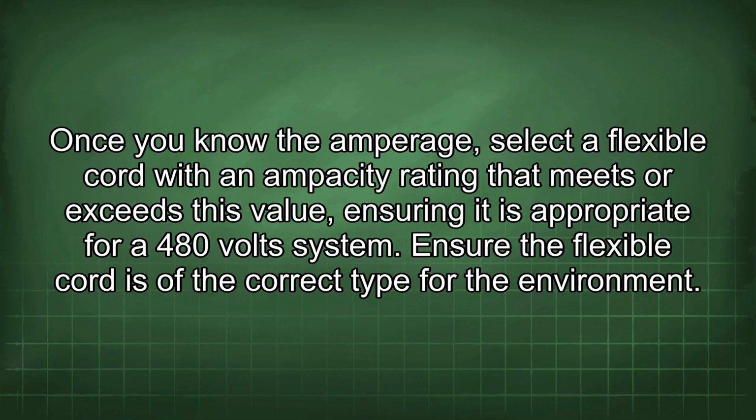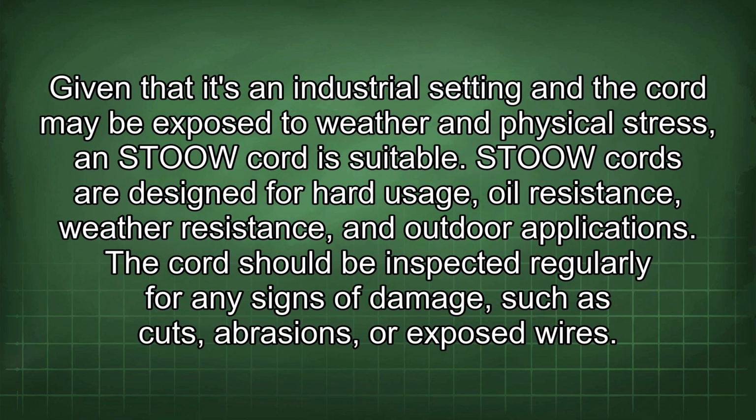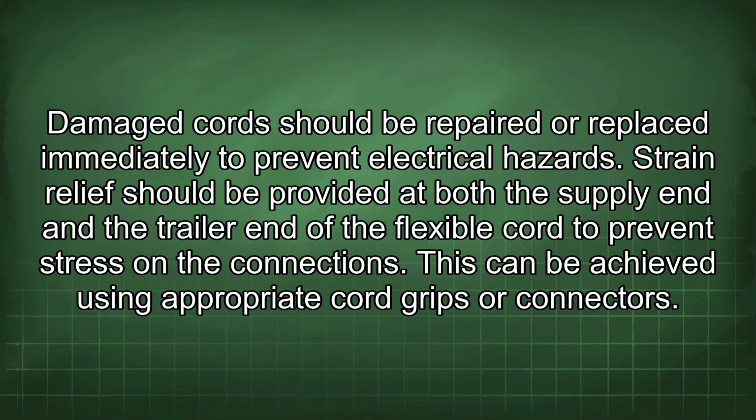Ensure the flexible cord is of the correct type for the environment. Given that it's an industrial setting and the cord may be exposed to weather and physical stress, a STU cord is suitable. STU cords are designed for hard usage, oil resistance, weather resistance, and outdoor applications. The cord should be inspected regularly for any signs of damage such as cuts, abrasions, or exposed wires. Damaged cords should be repaired or replaced immediately to prevent electrical hazards.